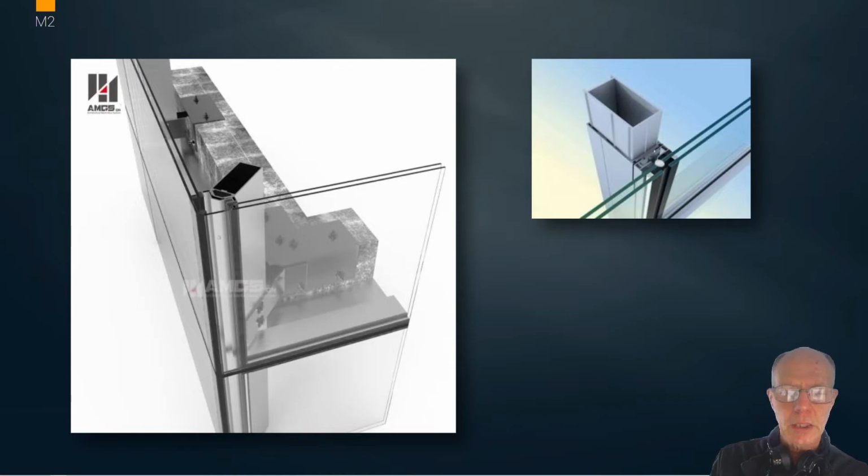In this case, the idea was to make these panels of glass as dominant on the feature as possible. So the glazed area, the place where the panels meet, is minimized to the point where there's actually not even a clip here any longer. There's just a silicone bead. And same thing at this corner. And you'll notice at this corner they held the glass all the way to the edge.